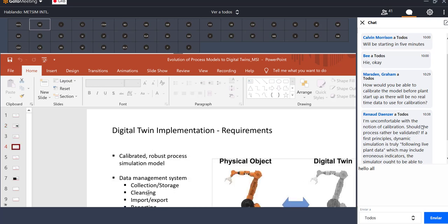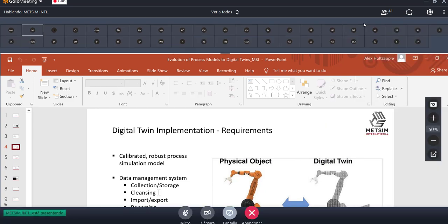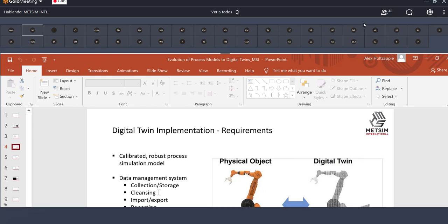We talked here about how data should be cleansed. So you say, how does Metsim correct for erroneous measurements? I'll take a quick tangent here and describe something that we have called soft sensor. Extremely valuable for very remote operations where, let's say you're measuring the pressure on a hydrocyclone and you know that it should be within, say, 15 and 20 PSI. That's where it's historically operated. And now that pressure starts coming back as 9,000 PSI or 0 PSI. Maybe the instrument went out.